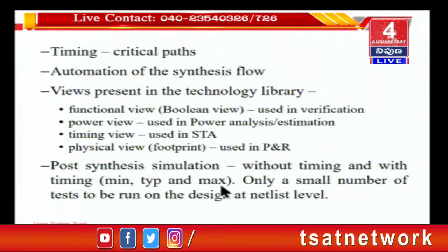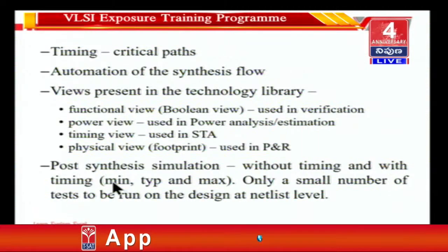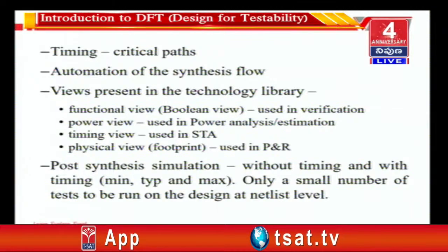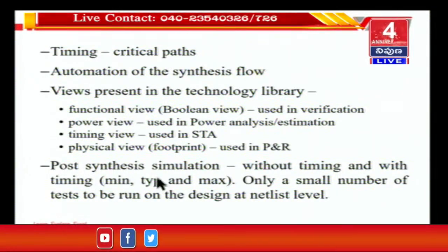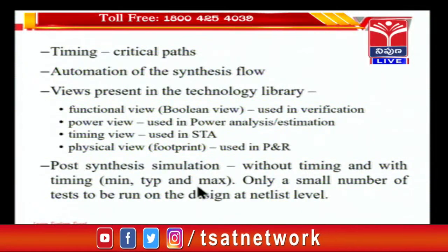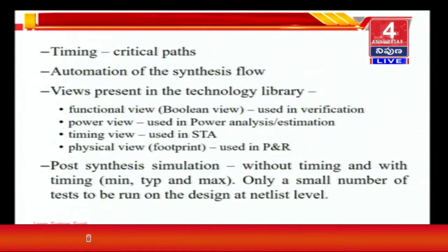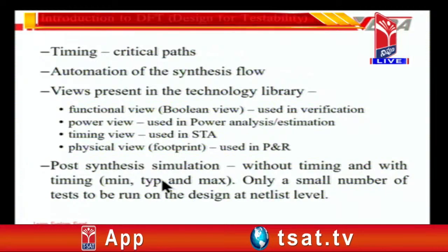However, if you say minimum timing, typical timing and maximum timing, there is a variation in the timing of each and every cell that has been characterized and will get manufactured. There is a minimum delay, there is a typical delay for most of the cells, and there is a maximum delay also. Therefore, if you want to really check whether the timing is being met or not, in addition to STA, you can also do it through simulation.